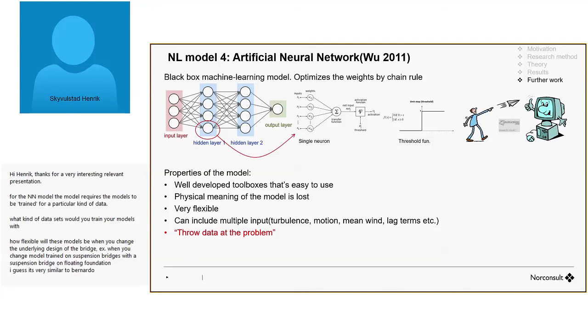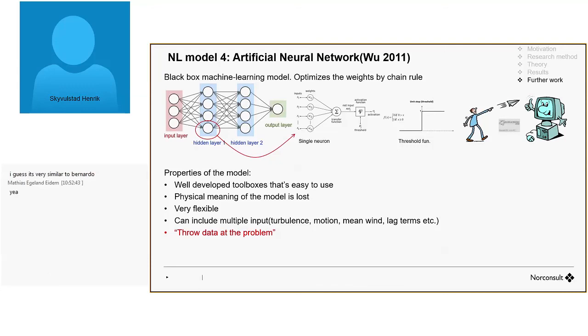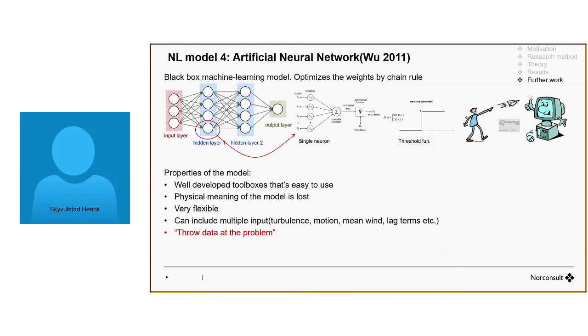Okay, so in our forced vibration rig, the eigenfrequencies of the actual bridge are not considered. We're just trying to cover a wide range of the reduced frequencies. So the way that we will train the neural network would probably be to have random motion going from low frequencies to pretty high frequencies, and then we're of course going to validate on another random motion test. But when we cover a wide range, this neural network is cross-section shape dependent. So you can use that cross-section on a suspension bridge or a floating suspension bridge. It's cross-section specific, not specific to the type of structure.